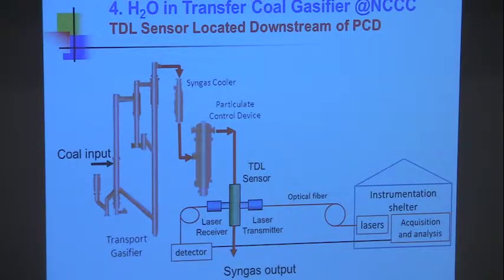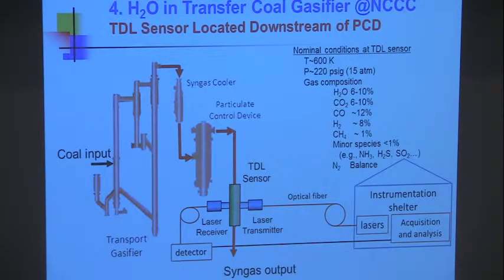By the way, the engineers there don't really want you there. They don't want any holes in their high pressure reactor. They're really paranoid about safety. This system is at, say, 15, 20 atmospheres, and it's hot. What happens if we blow a window and they have a hole in their system? They didn't like that. So there was all sorts of complicated optical design so that if one set of windows breaks, they could close the valve and so on. That took about a year, designing that.